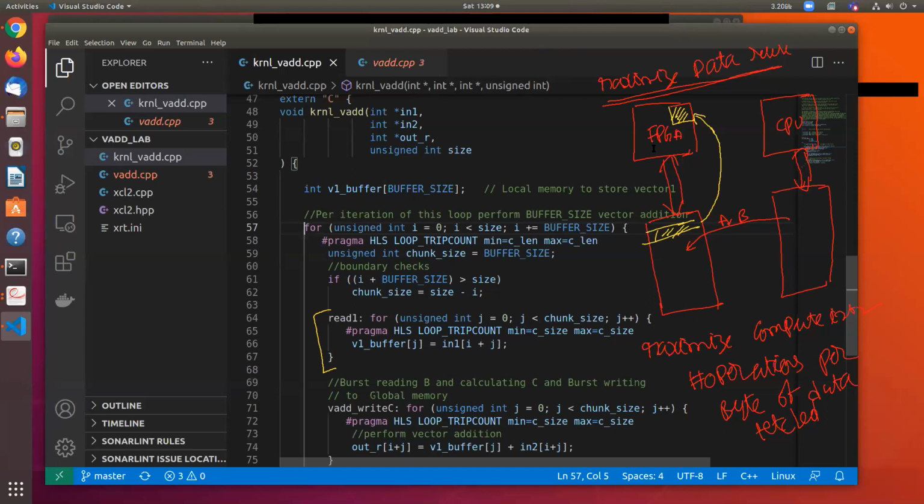Okay, so data transfer here is the most costly operation. So we are doing this to prevent that. It's costly, yes. The more you do data transfer from the host side, that is the most expensive operation. So ideally, the best way to parallelize is to take the data which is sitting on the CPU host and transfer it as quickly as possible to the DRAM sitting on the accelerator board. Whatever it is, it will still be faster for the FPGA to get data from that DRAM rather than from the host memory.